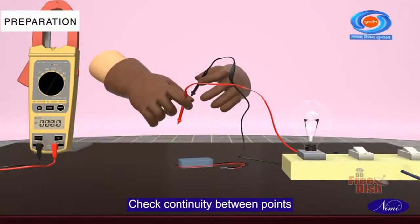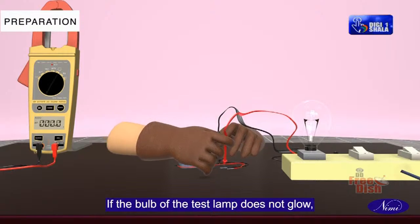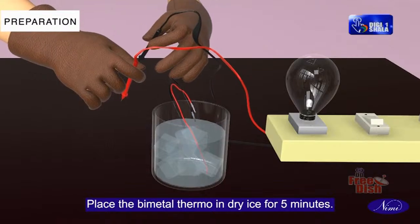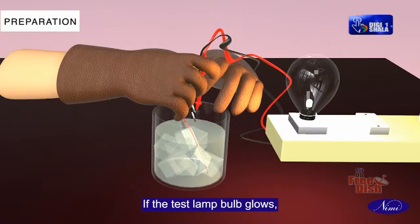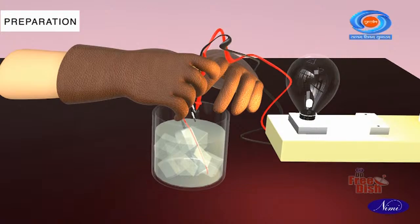Check continuity between points A and B of the bimetal. If the bulb of the test lamp does not glow, the bimetal thermo is functioning correctly. Place the bimetal thermo in dry ice for 5 minutes. After 5 minutes, check continuity between points A and B. If the test lamp bulb glows, the bimetal thermo is operating properly.